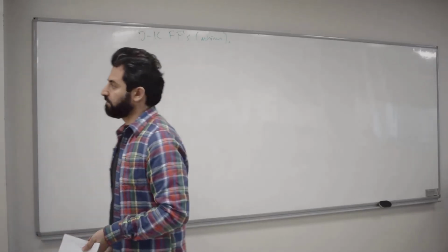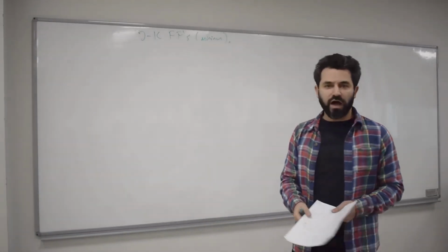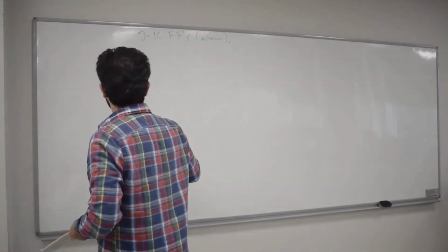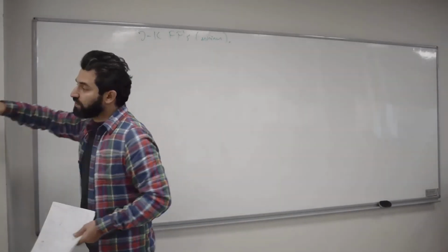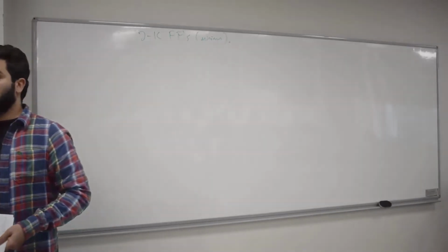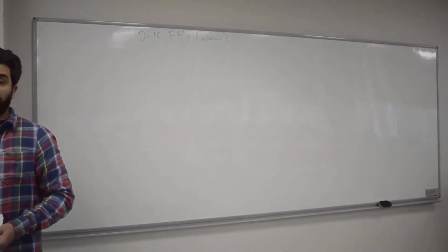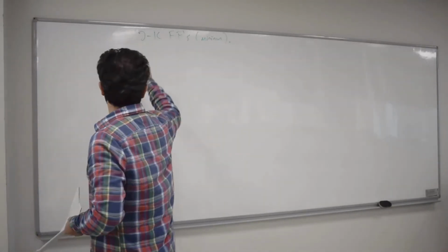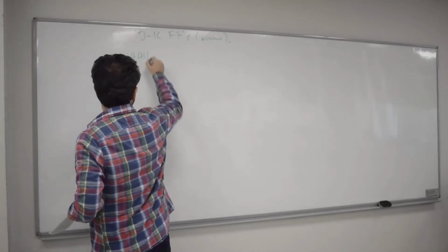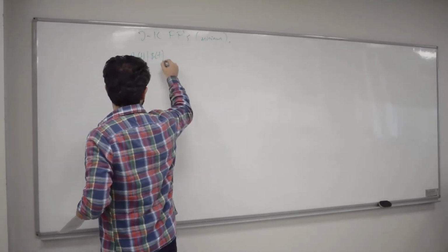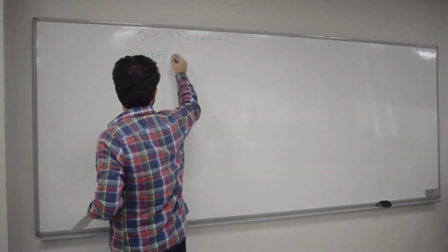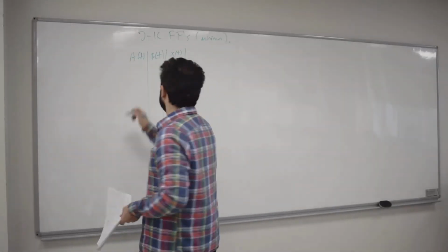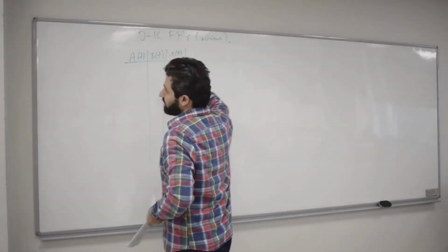Okay, the next thing you have to do from the state diagram is draw the state table. I have 2 states, in other words 2 bits, which means 2 flip-flops. So there are 2 flip-flop outputs, A and B. I'm going to use A(t), B(t), and X(t), which is my input, because I need a single bit for the input. The output is Y(t).